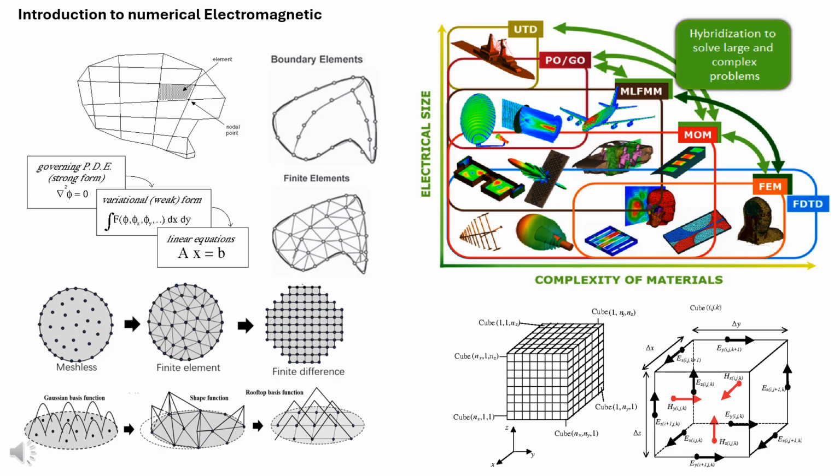In contrast, the BEM approach discretizes only the surface of the head model into boundary elements. The PDEs are transformed into boundary integral equations, simplifying the problem to a surface-based system. These integral equations are used to create a matrix system that, once solved, yields the potential on the surface of the model. From this surface potential, internal electromagnetic fields can be computed. The schematic shows the meshing process for both BEM and FEM, highlighting the discretization strategy used in each method.